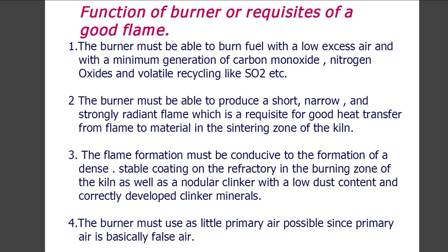The flame formation must be conducive to the formation of a dense, stable coating on the refractory in the burning zone of the kiln, as well as a nodular clinker with low dust content and correctly developed clinker minerals. The burner must use as little primary air as possible, since primary air is basically false air.